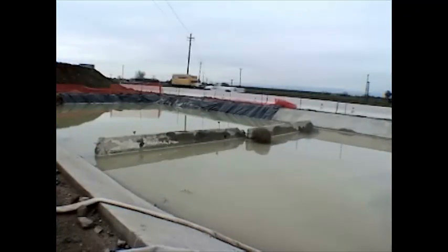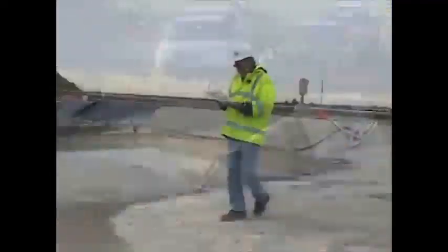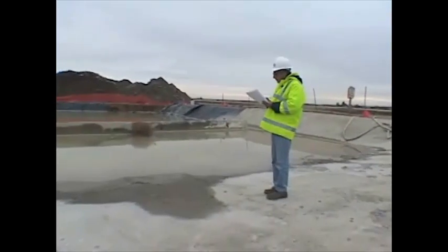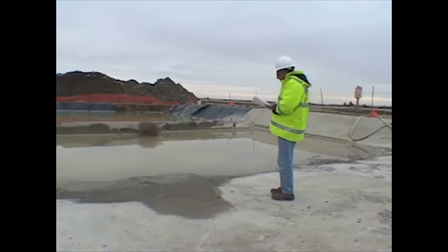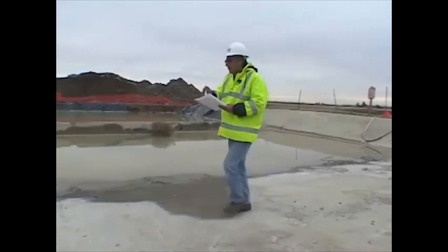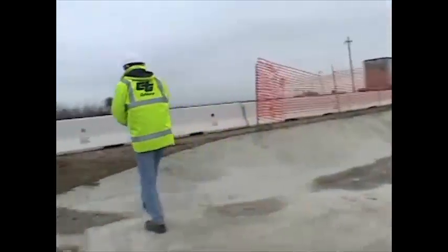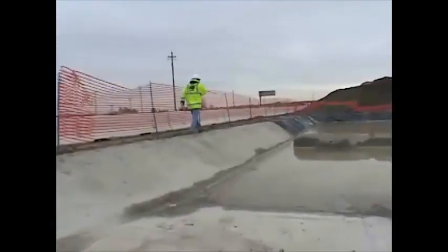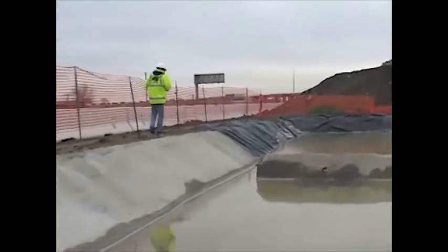Temporary concrete washout facilities should be maintained to provide adequate holding capacity with a minimum freeboard of 4 inches for above-grade facilities and 12 inches for below-grade facilities. Maintain temporary concrete washout facilities by removing and disposing of hardened concrete and returning the facilities to a functional condition. Existing facilities must be cleaned, or new facilities must be constructed and ready for use once the washout is 75% full.